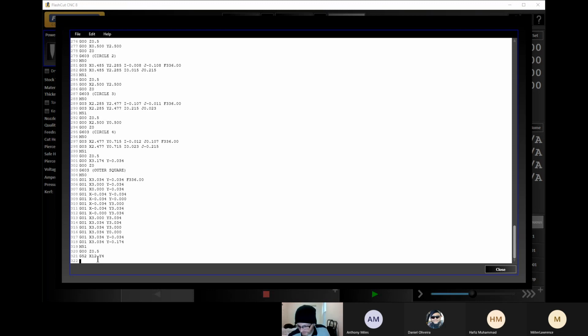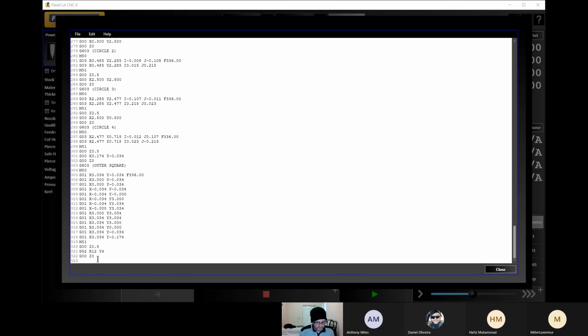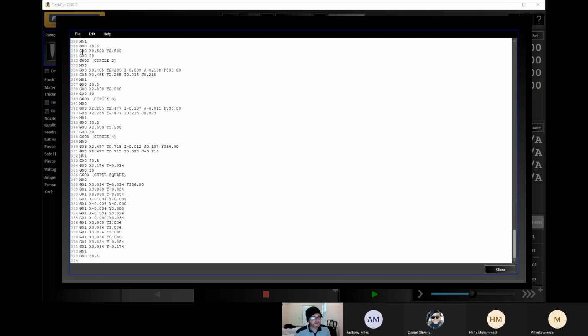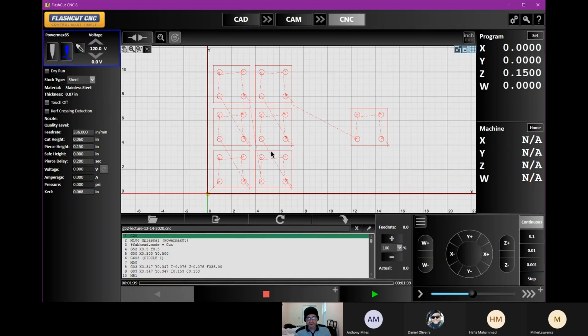All right, let me write down what line that started. Line 321. Okay. We lower our torch back down to the 0 position. We hit Control V to paste the programming. File, save it. File, close it. Now we put one out here.